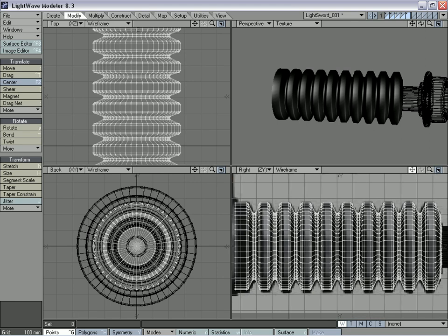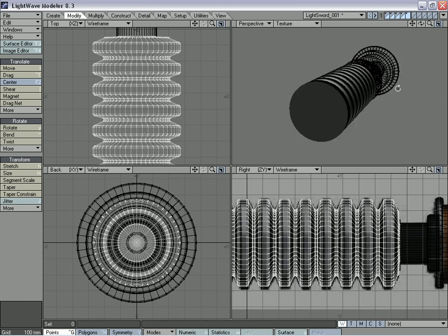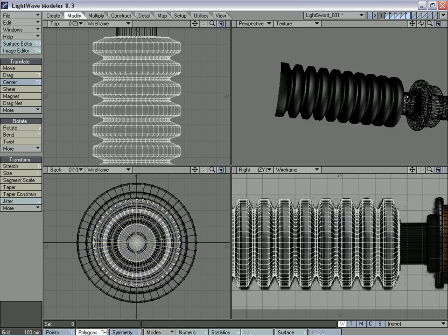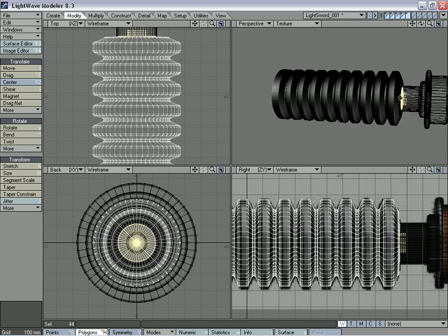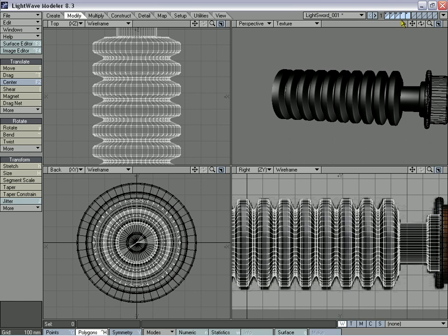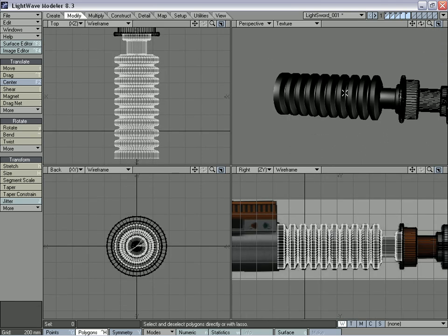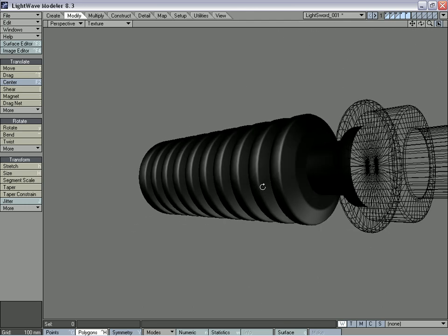And before we move on, we're going to define the surfaces of the rings, and delete, actually, these end polygons. Just moving around in a circle, making sure you select them all, verifying down here that you have all 48 selected, pushing delete. And I'm going to take a look at this one. Yep, we can delete those too, because those are inside. And pull that up full. Yep, that looks good.